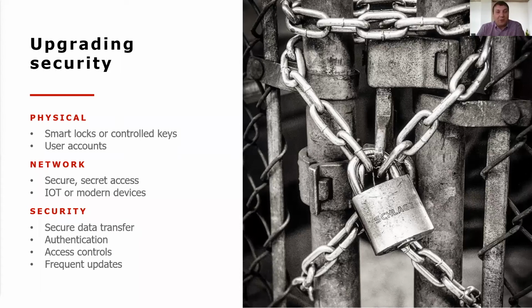And for that also, we need to have the ability to transfer data securely. Most controller standards are not secure when you look at the industry standards. So we have to look at private ways of doing that, not proprietary, but maybe using more modern connections and protocols to transfer our data, like HTTPS, SCP, things like that.